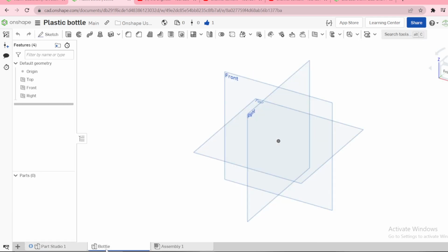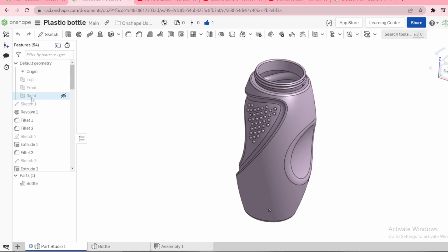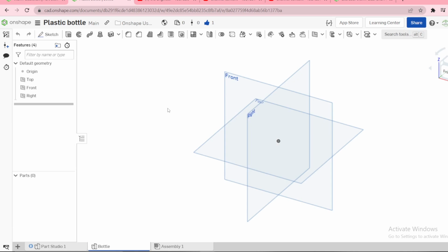The first thing we need to do is we need the main sketch. The main sketch here. You can see this sketch, the one I highlighted. We are going to start from the main sketch. Whenever you are designing a surface body, surface modeling, always start from the main body, then start subtracting what is not necessary. Therefore, I'll create a sketch on front plane.